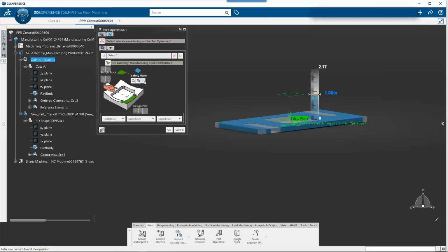So we'll click there. We can turn off that grid. You can keep it on or off if you want. You can also click on the number. So if I wanted that to be at an even 1 inch or 25 millimeters, if I'm doing it in metric, you can just click on the number of where it's at as well. So there's lots of interaction that's happening here.